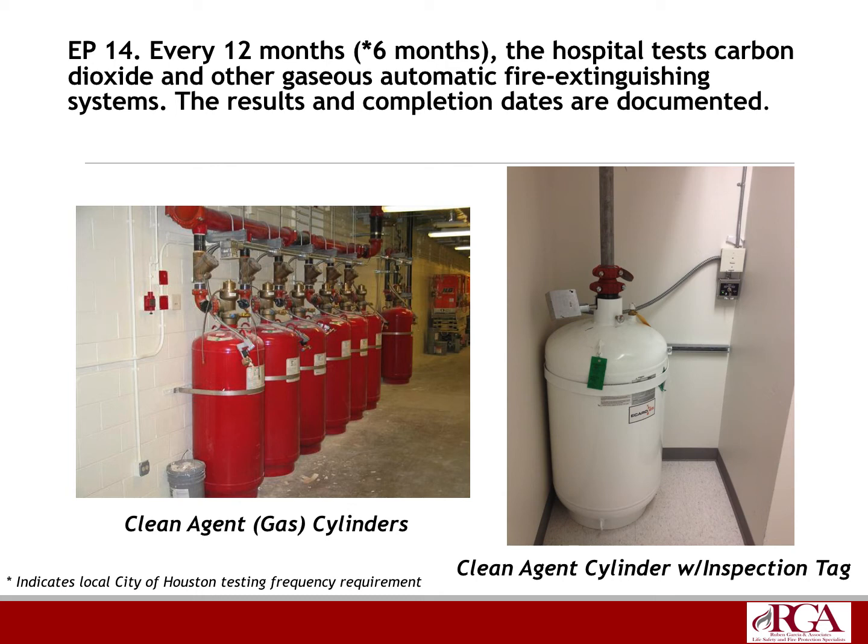These EP standards are the minimum requirements per the NFPA 2012 edition or NFPA 101 2012 edition. What you have to keep in mind is your local AHJ, your local fire marshal, may be going above and beyond, meaning they're on another standard, a different year edition that may require, for example, weekly testing of fire pumps. In this case, the city of Houston requires that we test these systems every 6 months. So we have to do them every 6 months to abide by the most stringent of those requirements. As we're going through the EPs, also check with your local AHJ and or the state, and sometimes even your insurance carrier might have different standards that you have to abide by. It's important that you follow the most stringent of all the AHJs that you have to follow. Sometimes you might just do best practice and do it a certain way based off your policy. So keep that in mind.